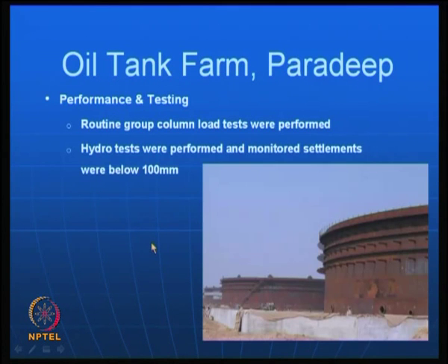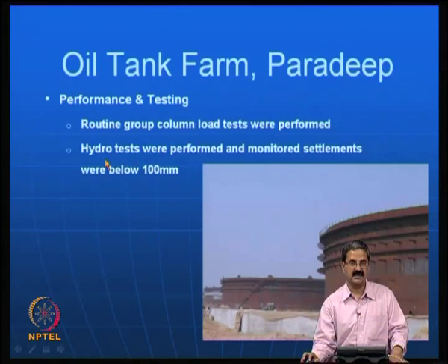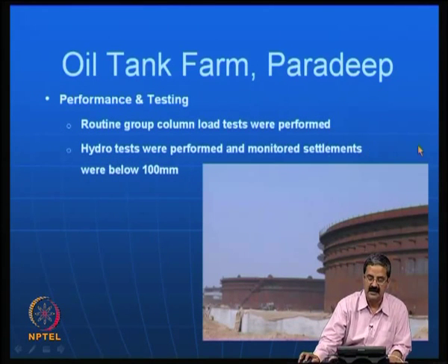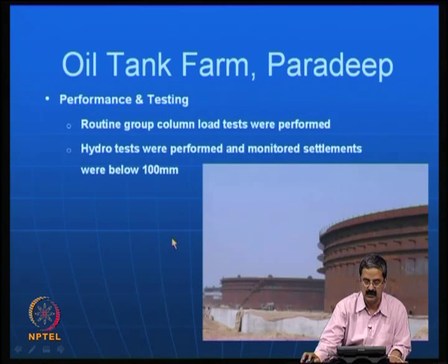So, routine group column load tests were performed for the stone columns. Group column tests and hydro tests were also done, and the settlements wanted were below 100 mm. That is one thing that was okay.